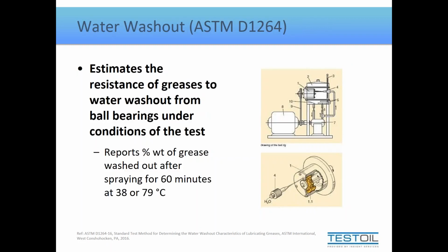Further, with our humid conditions, there is a water washout test, which is again a very set bearing that has been loaded with grease. You spray it with water directly into the bearing for an hour. At the end of the test, you measure how much weight was washed out of the bearing. It can be done at two different temperatures, so if you're comparing results, please make sure you're comparing tests done at the same temperature. It's the only way that the playing field is level there.